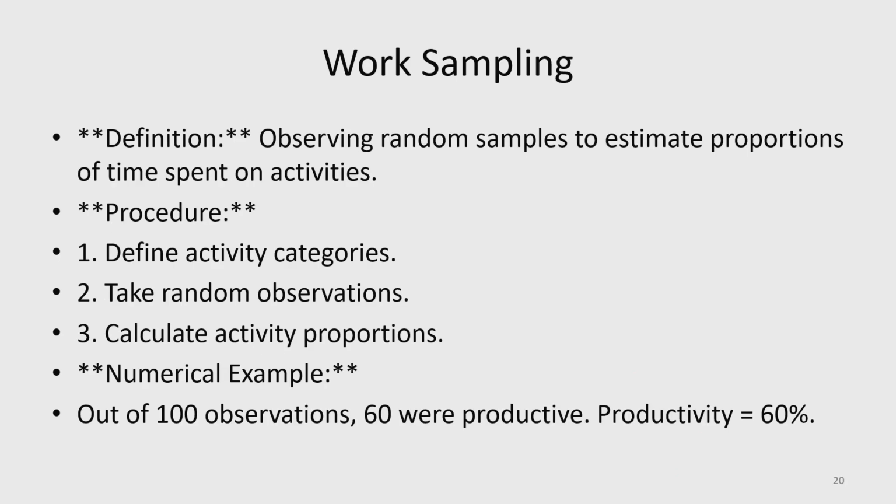So, this is just the measurement of the time study, and let me tell you that many times worker unions etc. may oppose the time study. They may ask why you are doing time study, and workers also become psychologically insecure. So, that is why in many industries time study is done with reluctance. They try to avoid that. But another method is there. If you do not want to do time study, you go to work sampling.